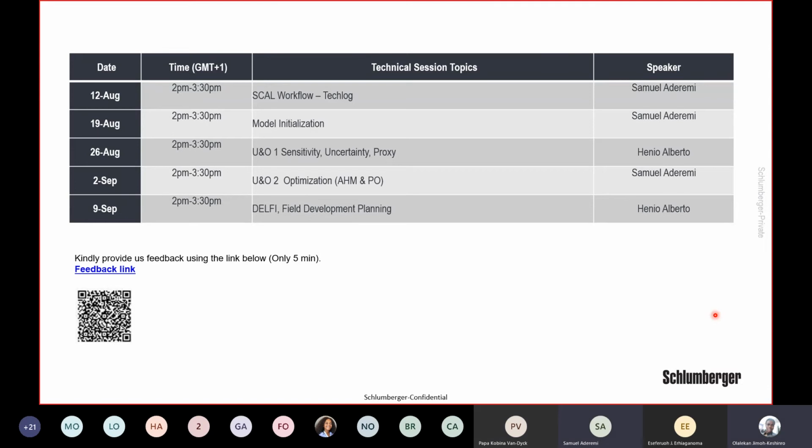So, Papa, for instance, your solution gas-oil ratio above the Psat should be a constant value. And we know that the simulator requires monotonicity of the table that you are bringing in. So if you really want that appearance, you can make a little adjustment, especially if you perceive that your convergence issue is associated with it.